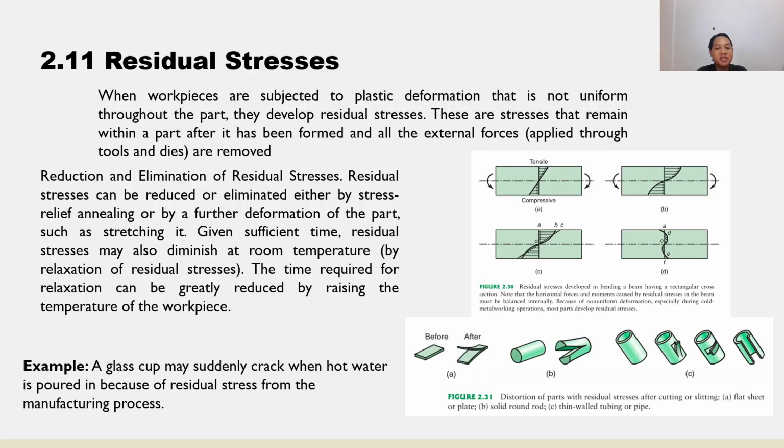Residual stress can be reduced or eliminated either by stress relief annealing, or by a further deformation of the part, such as stretching it. Given sufficient time, residual stress may also diminish at room temperature. The time required for relaxation can be greatly reduced by raising the temperature of the workpiece.